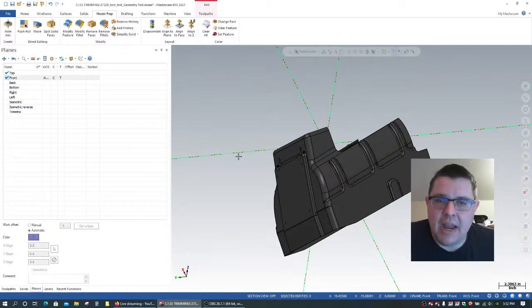I don't think it has any bearing on the quality of the geometry. So I want to make that distinction: the quality of the geometry that you import is not dependent on its position in space. Its position in space is independent of the quality of the geometry. Normally the quality of the geometry is dependent on the export tolerance that the guy who exported the model used